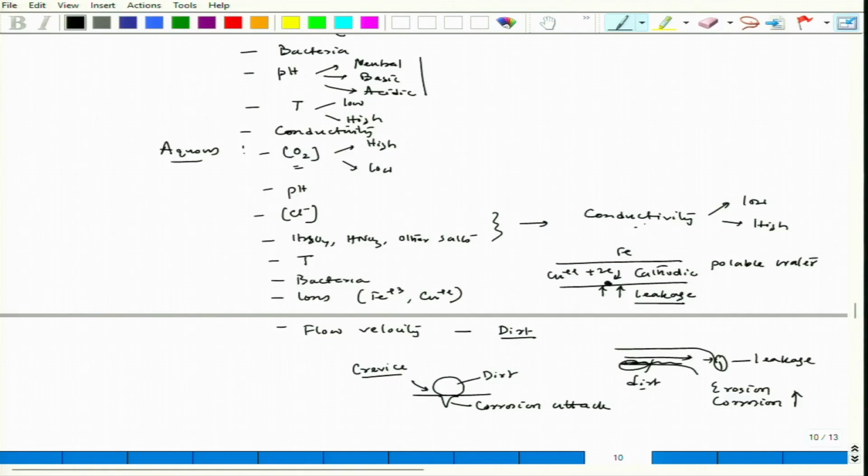So, we have to think about that as well. In most cases the protection is a bit concentrated, and those protections are costly because we have to change the material. Generally ferritic or magnetic steels are good at resisting swelling. So, we have to use those costly steels for the operation of nuclear plants. Again, everywhere we see that radiation is coming into the picture.